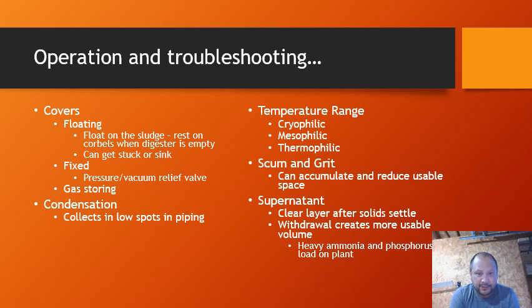And then we have two other digesters that are storage digesters. And we will pump sludge from the primary digesters to these secondary digesters. And if that sludge is allowed to sit there for a few days, the solid material sinks to the bottom, and sometimes there will be a relatively clear layer of water on top, and we can draw that water off the top and send it back through the plant for treatment, which is, of course, cheaper than running it across our belt filter presses.